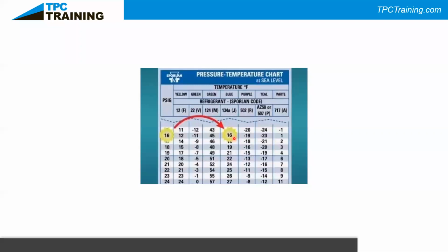Pressure affects your saturation. For those who are joining us, I live in Pennsylvania. Water needs to get to a temperature of 212 degrees Fahrenheit before it begins to boil. Those who are joining us from Denver, Colorado, you're a mile higher than the elevation where I am, so your water might boil at 205 degrees. What we're showing you is that by manipulating the refrigerant and causing it to a lower pressure or a higher pressure, we can cause it to change state at different temperatures. And it's important to know what refrigerant you have and what pressure you have using your PT chart.